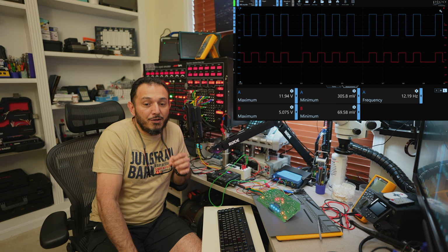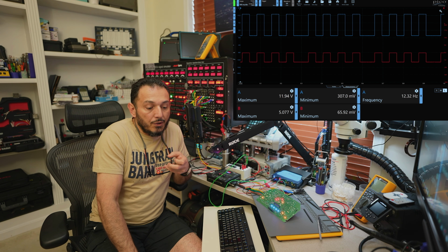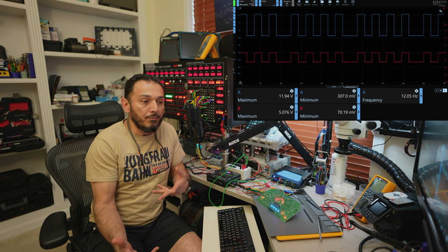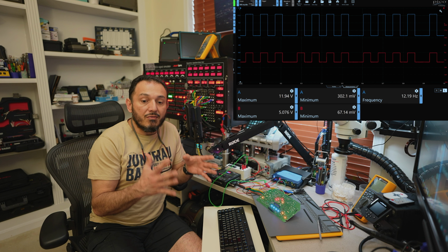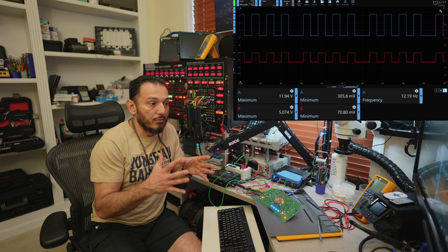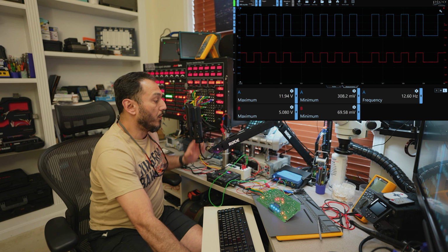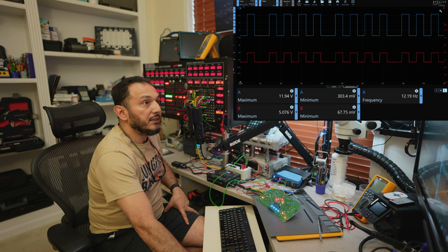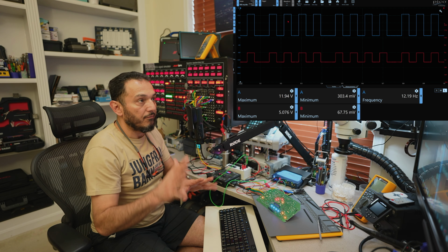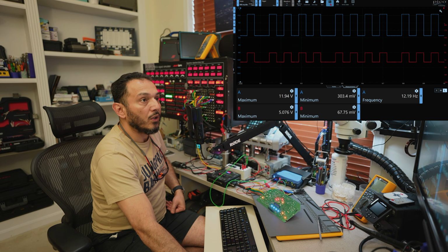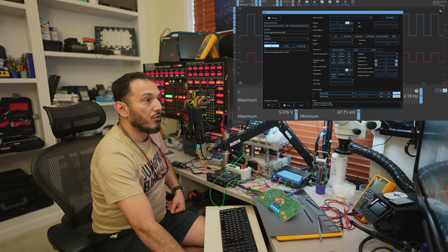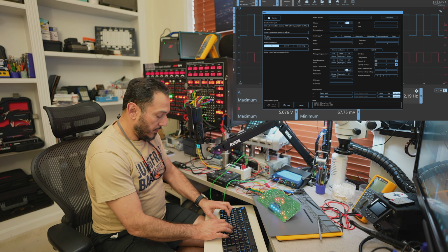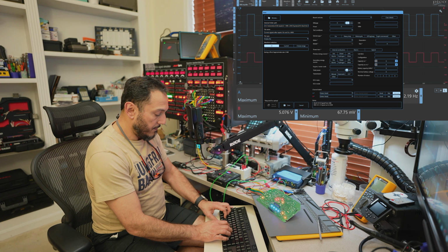It's 100% fixed. So thank you, Greg, for talking to me to help me gather the correct information so I can also help you. And also now we are gathering the correct data. I got completely the correct data. The other thing I want to do with you is stop this capture, and run one more time just to collect one screen, because I want to save this. This is a correct signal after repairs: 12 volts and 5 volt square.